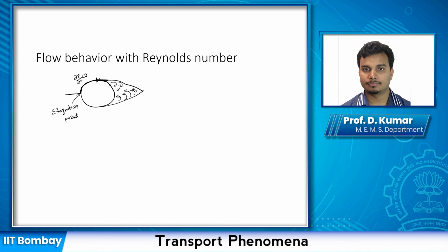Now, since the wake region is large at this instant, the contribution from pressure drag is dominant, so to say. Not just significant, but dominant. The major contribution to the total drag actually comes from this pressure drag, because of the large wake formation, and this happens at large Reynolds number, like 10 to the power 5 or so.